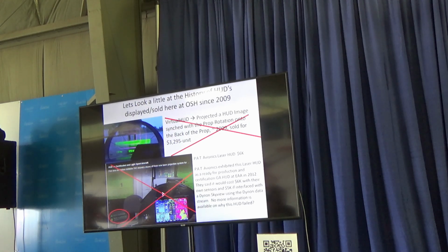Well, the Epic Optics HUD is great in certain ways, but it will not fit in most RVs. You know, an RV-14, an RV-4 has at the most maybe an inch of panel space where the canopy comes down in the front. So it's not even really a question using that in those aircraft. The AR glasses can be used in most any type of aircraft. And there's a number of folks using the AR glasses now with our software.